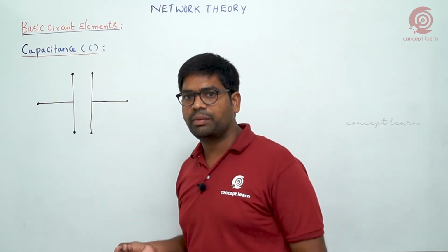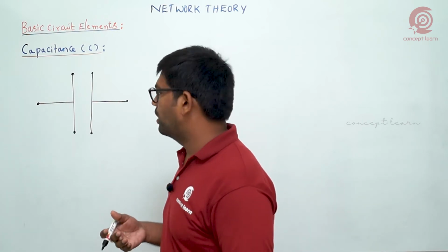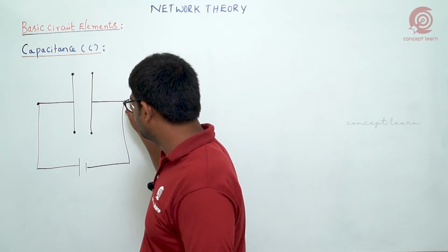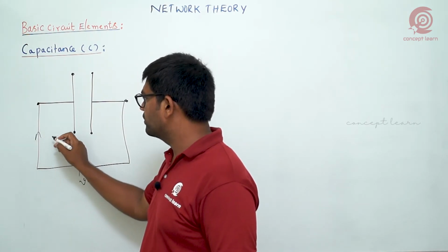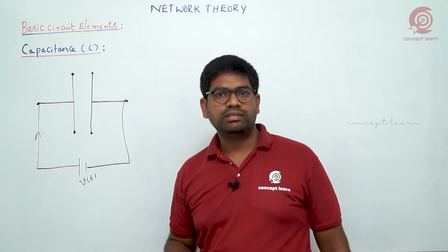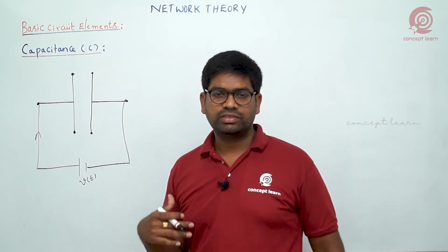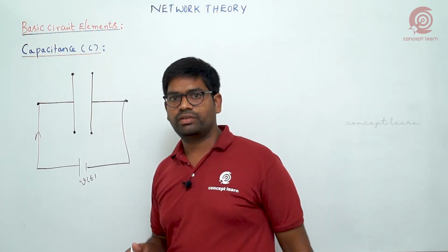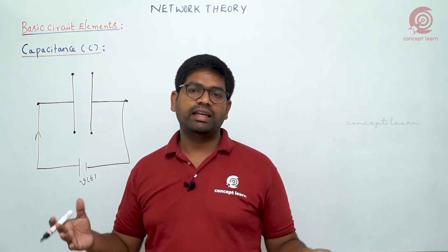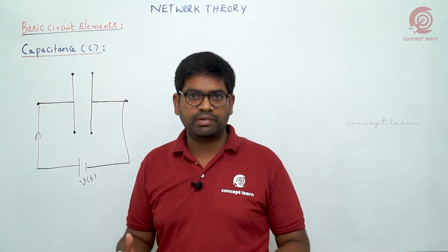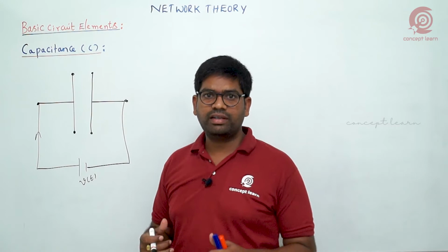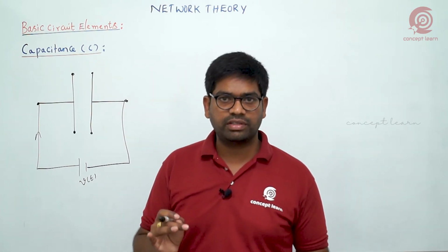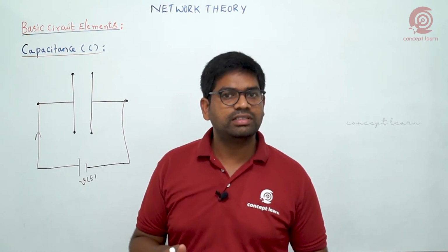It can acquire some amount of charge in the form of a field. So how are you giving energy to this? When you apply energy in the form of voltage v(t) to this, then current will be flowing through it. But a capacitor only allows alternating current. DC current it does not accept, so it works only for AC current, you can say, in the steady state portion, when time is changing. Got the point? The initial state and steady state, that complete behavior we observe in that special topic, the transient behavior. But at this moment we are only focusing on steady state behavior, and mainly writing the voltage, current, power and energy relations for all these three basic elements: resistance, inductance and capacitance.